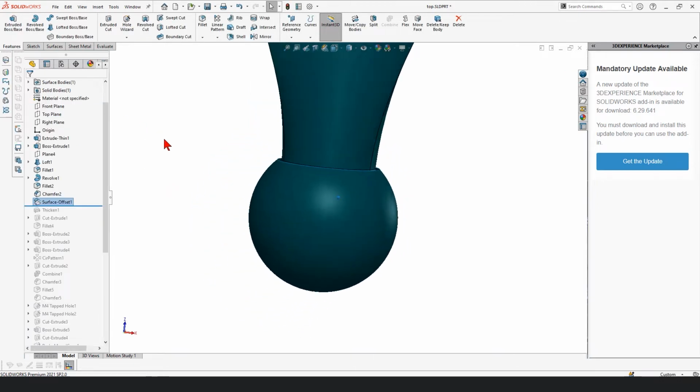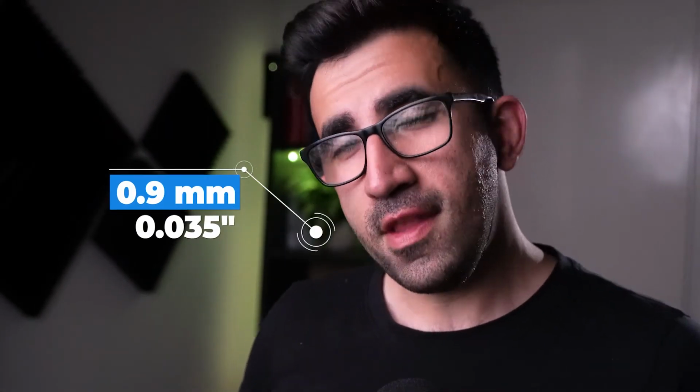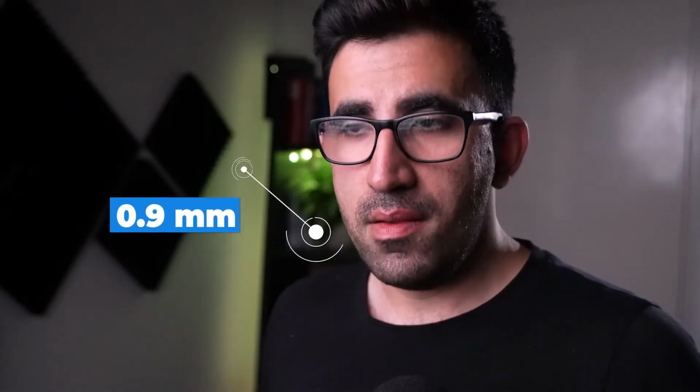Unlike the previous pocket that was too rough, where I could just make whatever I want, this one cannot be too big, because otherwise the ball would be too loose in the pocket. And I went with 0.9 millimeter. Again, based on experience from each side, I think that's a good amount, because in the worst case scenario, the ball has less than 2 millimeters to move in each direction.